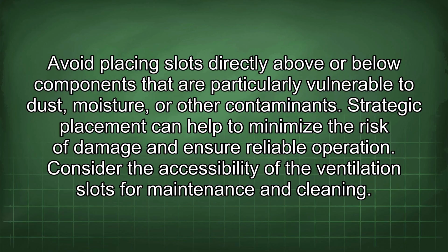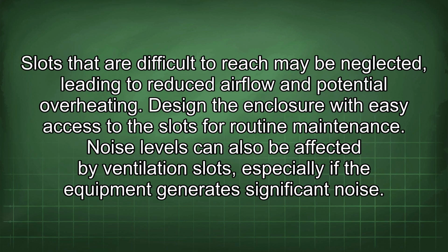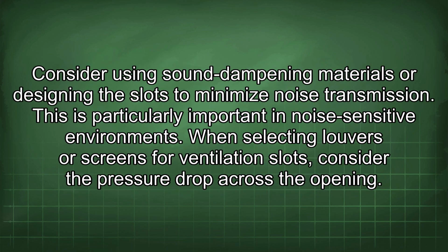Consider the accessibility of the ventilation slots for maintenance and cleaning. Slots that are difficult to reach may be neglected, leading to reduced airflow and potential overheating. Design the enclosure with easy access to the slots for routine maintenance. Noise levels can also be affected by ventilation slots, especially if the equipment generates significant noise. Consider using sound dampening materials or designing the slots to minimize noise transmission. This is particularly important in noise-sensitive environments.